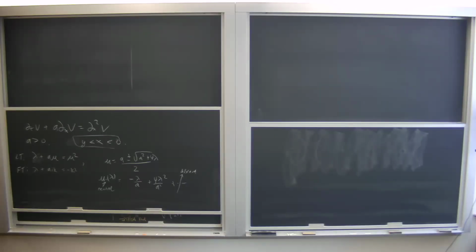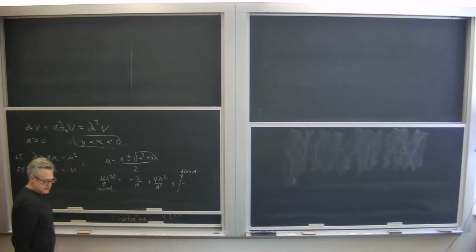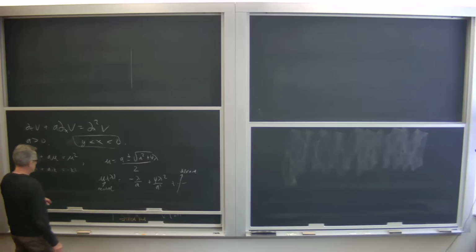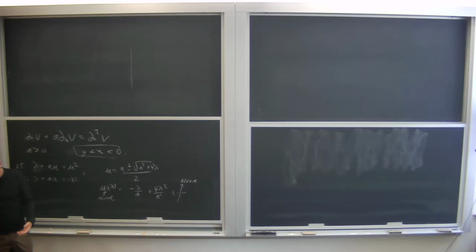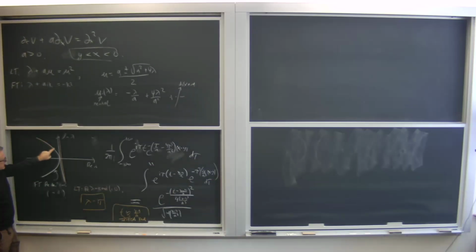Looks good. Okay, so before going on, I wanted to amplify a remark I made at the end. I did an extensive study of the constant coefficient scalar convective heat equation here. I've rewritten it for you. Convection rate a taken positive, and we did it by relating to the Fourier transform. And the way we did that, we moved a contour onto the dispersion curve